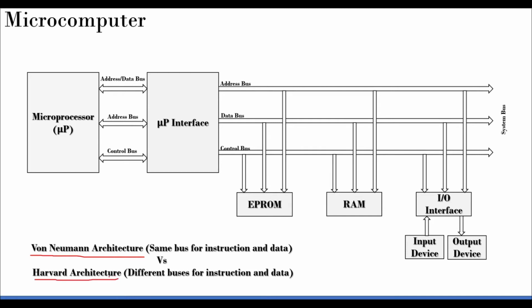It's a very interesting concept, and very simple. Actually in von Neumann you don't have a separate data bus and address bus. You have the same bus. In fact our own 8-bit microcomputer that we designed belongs to the von Neumann architecture, because we only have one bus for both the data transfer and the address transfer. Remember that the instruction was also using the same bus and the data was also carried using the same bus.